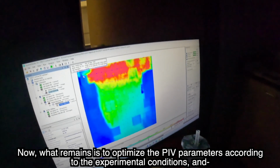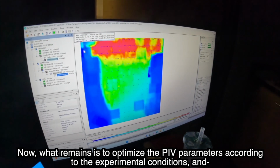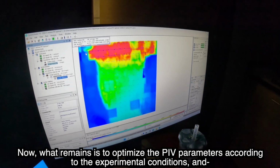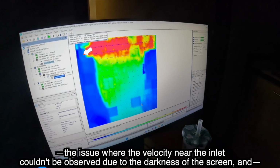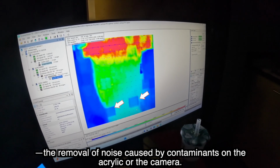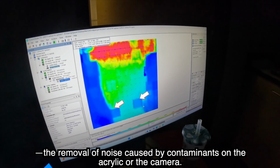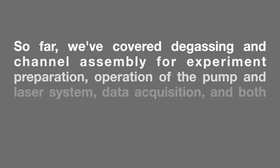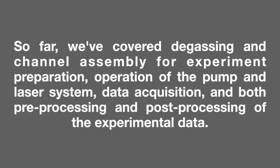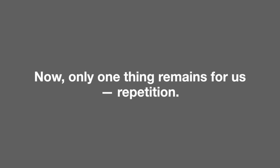Now, what remains is to optimize the PIV parameters according to the experimental conditions, and the issue where the velocity near the inlet couldn't be observed due to the darkness of the screen, and the removal of noise caused by contaminants on the acrylic or the camera. This concludes the tutorial video on the PIV experiment. So far, we've covered degassing and channel assembly for experiment preparation, operation of the pump and laser system, data acquisition, and both pre-processing and post-processing of the experimental data. Now, only one thing remains for us: repetition.